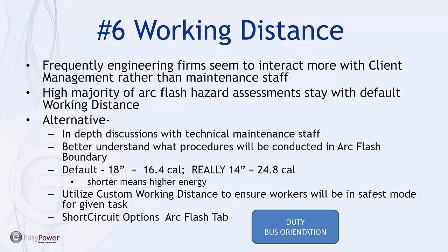And we find frequently that people use the default dimensions, which are in the tools, which is 18 inches, and I'm not really sure why this is the case, other than that engineering firms are usually interfacing primarily with management, and quite often the majority of the arc flash assessment stays with the default working distance.